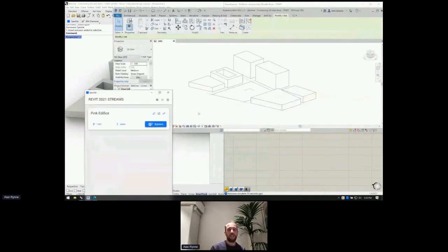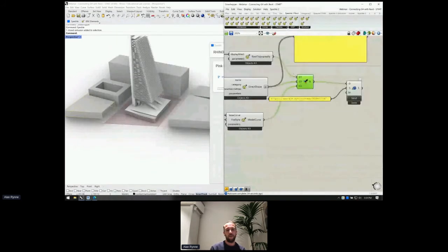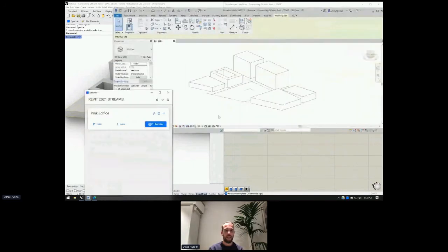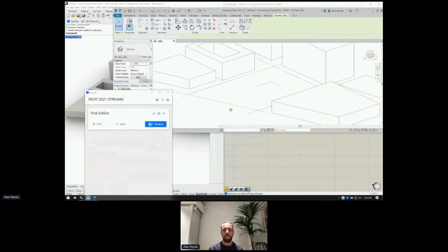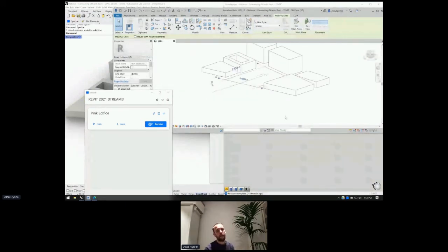with everything else. Notice that I'm incrementally adding to my objects that I'm sending, so that I'm sending everything at once, because every commit, every time I send, is like a snapshot of the entire model that I want to generate in Revit. So now we have our nice curves in Revit that are actually native curves that you could actually edit if you needed further here.